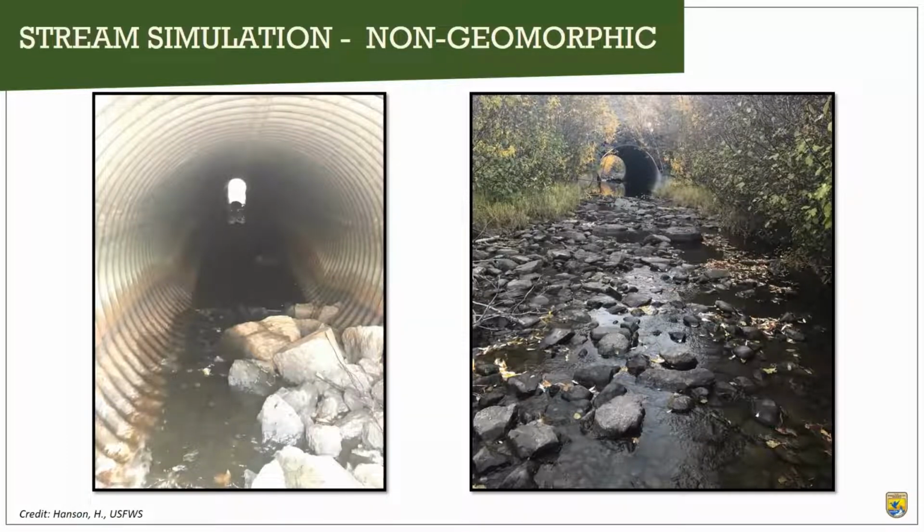These usually don't work. The culverts are sized based on active channel width or the ordinary high water width and our design flood. So they are usually not as big as the bankfull channel width. And we are not using bankfull geometry or geomorphic principles. You can see for this culvert, the result was that all this substrate that used to be inside the culvert was washed out and is now disrupting the channel geomorphology downstream.